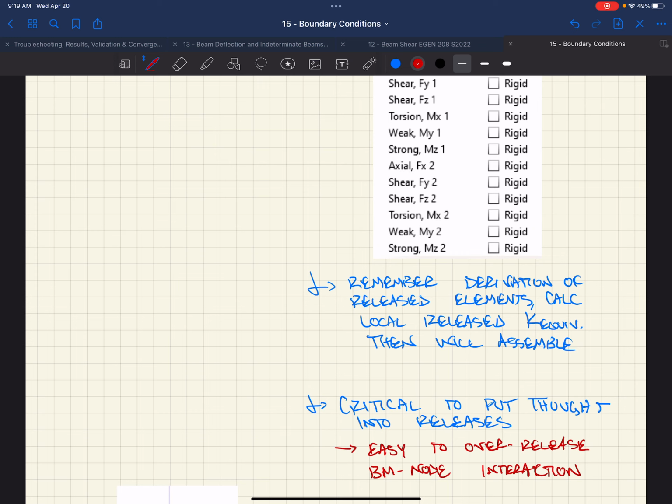And so at this intersection, all you're doing is making a transition in stiffness, in size and strength. So all you're doing is, okay, now I have, say, a W16x46, and then here they model it as something else, maybe a generic blob or some sort of shape. Can you just use a rigid length for that? You can, but you've got to be careful, because then you're saying it is infinitely stiff. Is that as accurate as you want it to be? Because that's affecting the overall stiffness of the entire frame.